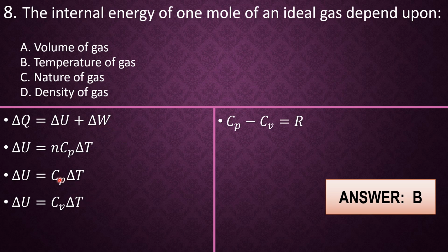But you notice that Cp is actually greater than Cv, and is actually greater by this amount: Cp minus Cv is equal to R, because I just talked about heating a gas at constant pressure and heating the gas at constant volume. But it's worth noting that the heat capacity of the gas at constant pressure is bigger than the heat capacity of the gas at constant volume, and it's a past UC question for candidates to be able to explain why the heat capacity of the gas at constant pressure is bigger than the heat capacity of the gas at constant volume. Just come back here.